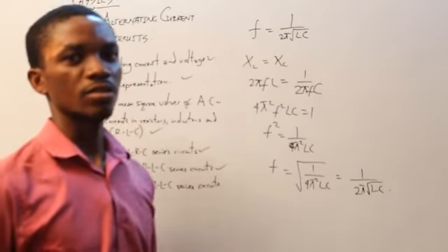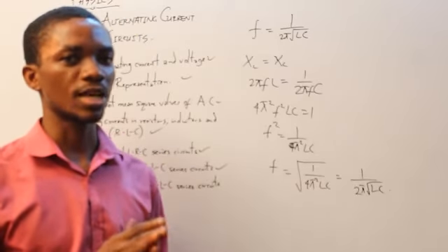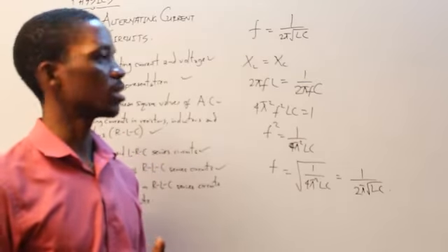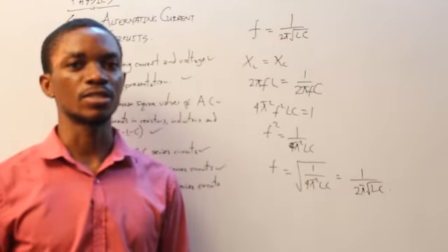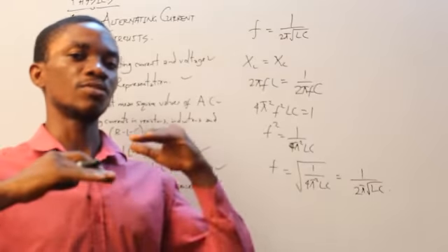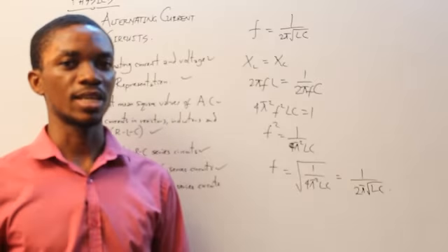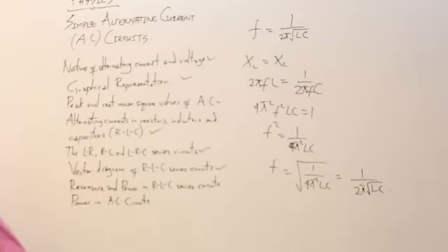We get the frequency at resonance. Frequency at resonance means the capacitance and inductance have no effect on the system. In other words, at resonance, the current and the voltage are in line with each other. They are not at any angle from each other.